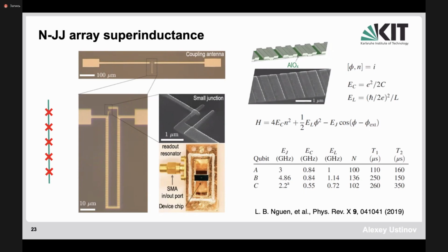Now, if you do it on transmons, the frequency is roughly 10 gigahertz, and technically, it's impossible to generate a digital profile at this very high frequency. So what people use there is upconversion in frequency. They have a local oscillator and a mixer, and this mixer is modulated by the digitally generated signal in the band roughly from 0 to 1 gigahertz. Then this frequency is added to the frequency of the local oscillator, so this pulse is basically upconverted to roughly 7-8 gigahertz.